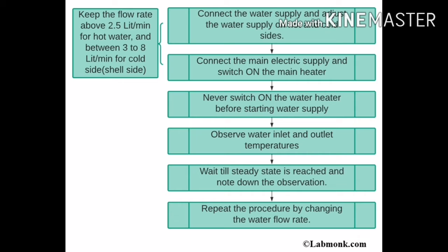The main objective of this experiment of my report is to determine the performance test, and also we can discuss the safety precautions while operating the heat exchanger. The requirements in testing the parallel flow and counterflow are the heat exchanger first, the valves for flow and direction control, thermometers, either 5 pieces, maybe 4 pieces, measuring flask, and a stop clock.